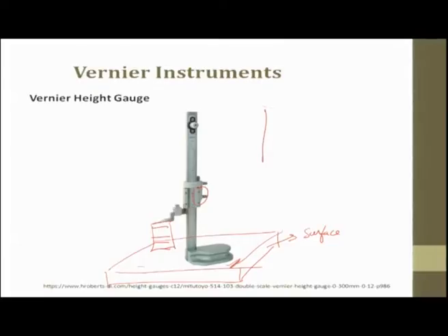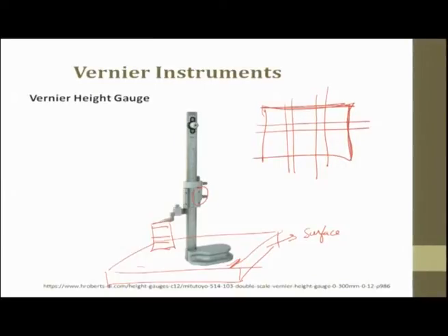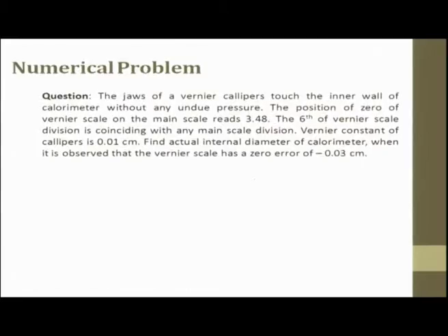For example, if you have a flat plate and you want to measure and draw lines for some applications, then we machine this workpiece and make the surface flat, keep it on a surface plate, use the height gauge and scribe the line on top of the surface so that we get the marking. With this, you can either punch or do any operation of your choice for further machining.